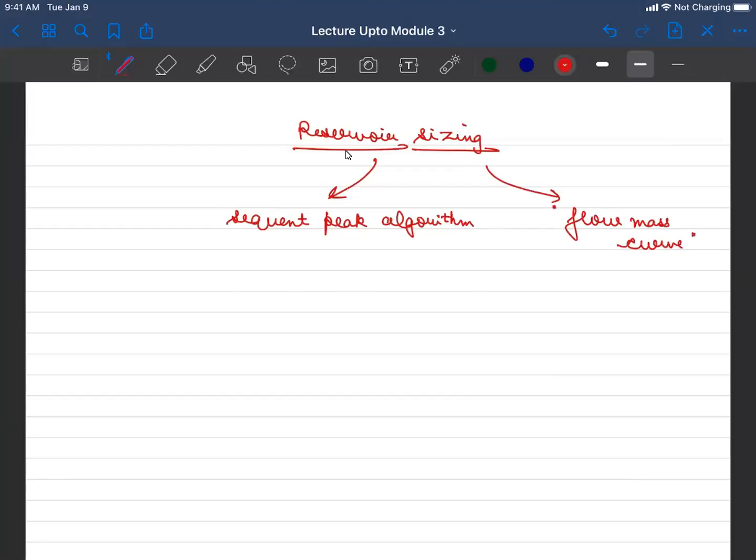That is, we can say that we will look for the maximum deficit at any time t, right? And that maximum deficit should be the deficit at the previous time step, plus you may create more deficit by releasing water if you have more demand, minus what is inflowing. So basically, last time you had a deficit of 5, now people are asking for 5 more units of water and you only got 2 units of rainfall. So your deficit will increase.